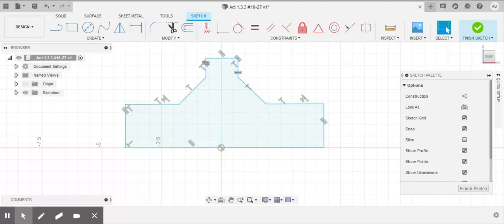Okay, so I'm going to click, see on the right here where it says construction. Well, first I got to click on line. So click on the line tool. All right. And I want to make a construction, and it's going to be the midpoint. Notice for the midpoint, it's trying to click the midpoint as that little X right there. And the midpoint is that little plus there. Okay. So those right there, those are midpoints.